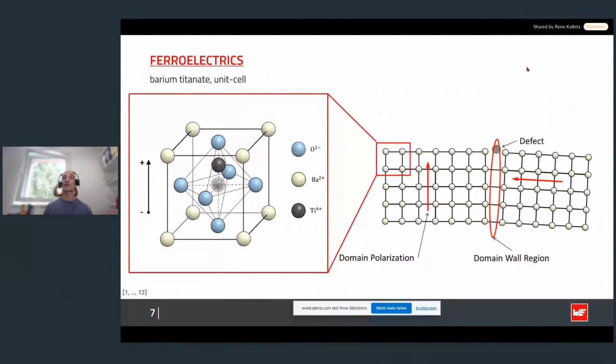The term ferroelectricity is used in analogy to ferromagnetism, in which a material exhibits a permanent magnetic moment. It describes the property of a material to form electric dipoles without applying an electric field. Ferroelectricity only occurs in crystals that have a unit cell with no center of symmetry, that is to say, a non-centrosymmetric shape.